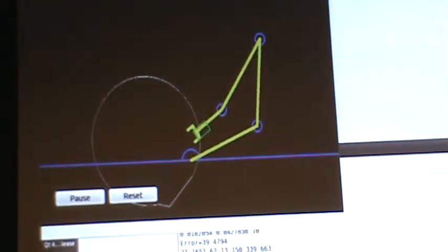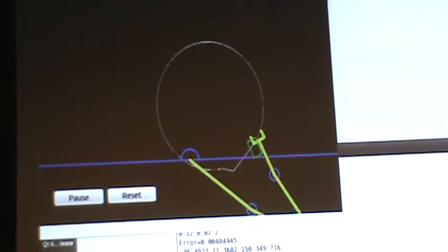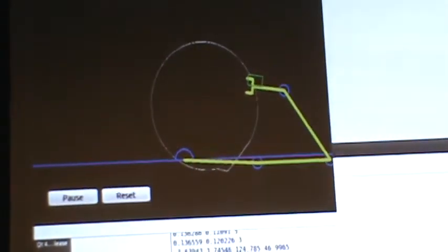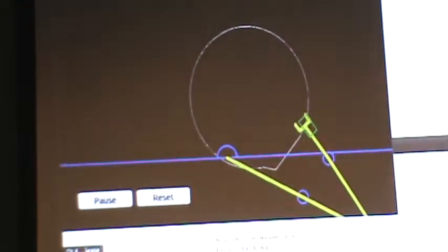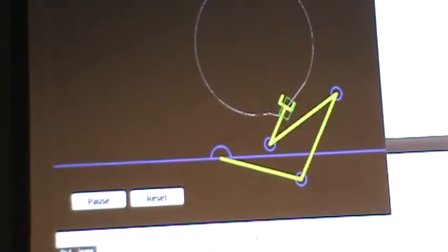Without this, you sometimes get solutions that end up as not a number because of arctangent. These functions are very notorious. If you don't condition them well, you get very bad solutions. And certain kinematic solutions are better than others for calculation purposes.